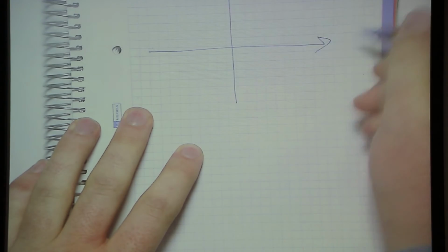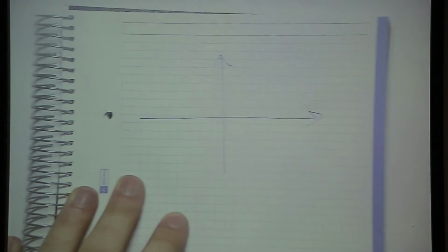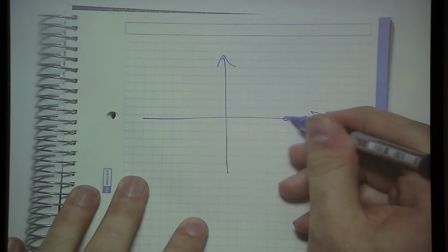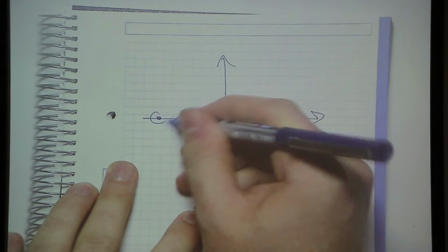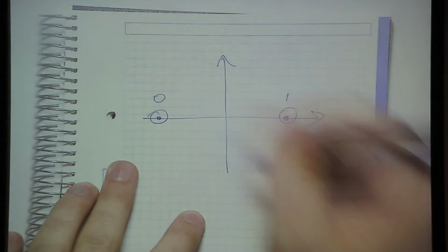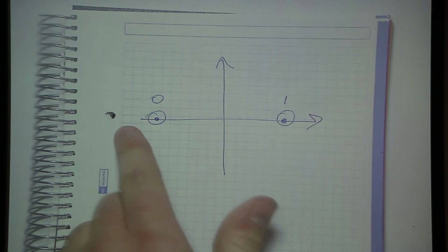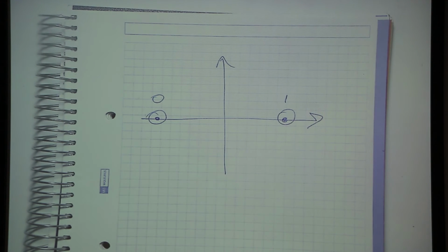And you just say, right, here is our IQ plot. Then our transmitted signal will be either at this point or at this point, and we'll call this a 1 and this a 0, and we can transmit binary by just moving between these 2 points. At any moment in time, if we're at the 1, that's a 1 being transmitted, and if we're at the 0, that's a 0 being transmitted. And then it's easy to make this a little bit more sophisticated.